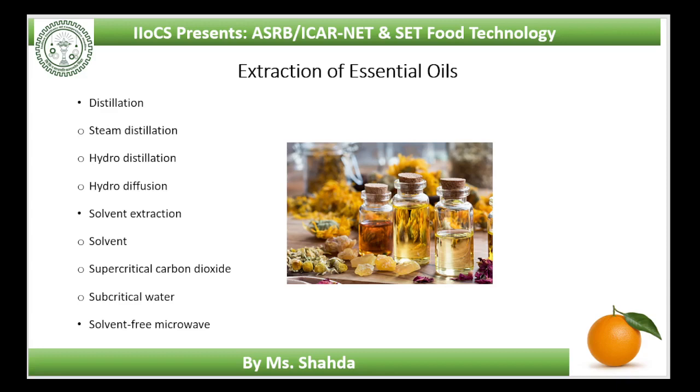Therefore, supercritical fluids have been considered as an alternative medium for essential oil extraction. Carbon dioxide is the most commonly used supercritical fluid because of its modest critical conditions. Under high pressure, carbon dioxide turns into a liquid which can be used as a very inert and safe medium to extract the aromatic molecules from raw materials. No solvent residue remains in the final finished product, since the liquid carbon dioxide simply reverts to a gas and evaporates under normal atmospheric pressure and temperature.